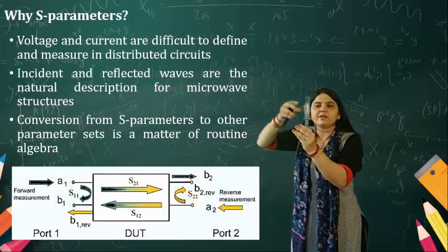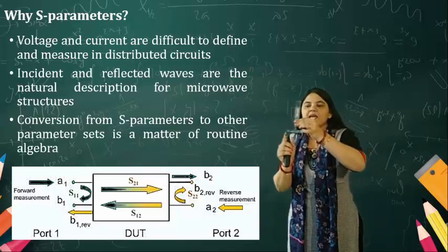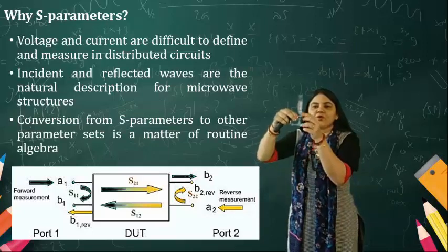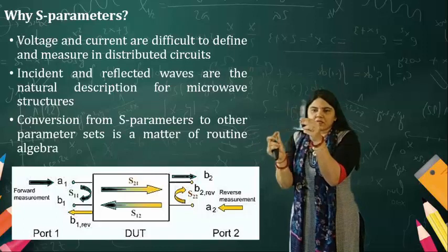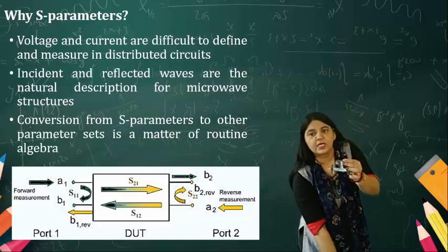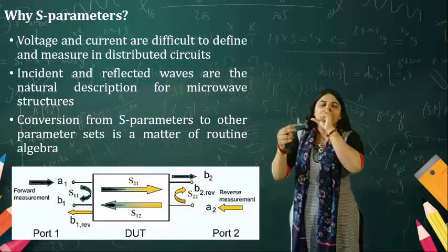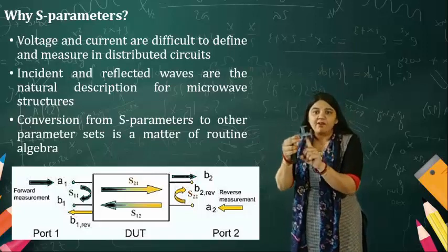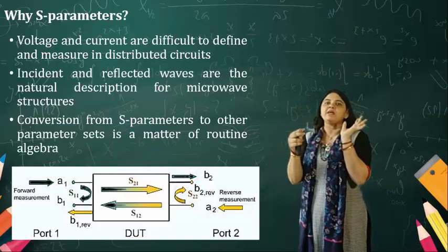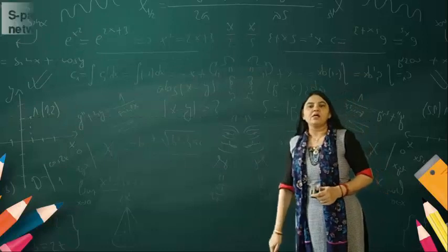Similarly, if I am connecting my match load over here, what do I have? I have the match load here. If I am applying the input from this port, I have output from this port. So you can see over here, this is my device under test. If I want to find out the behavior of this component, I should have an idea about the S parameter. You can see over here.